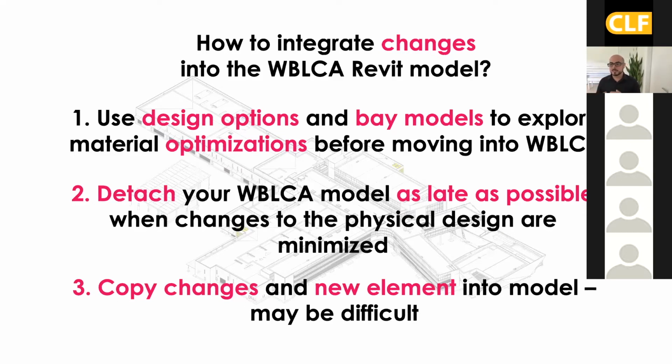So by the time that you are doing your whole building LCA, you've already figured out many of the details, and it's less likely that you need to make changes. The second, as I mentioned, is to detach your model as late as possible so the changes are reflected. The changes in the Revit model are reflected into at least one model, and then you detach it and create the baseline or the proposed, or vice versa.